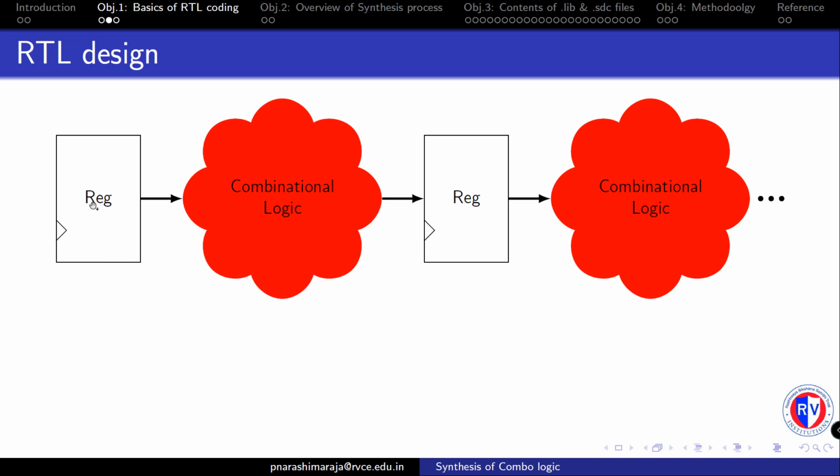One is the registers, which is a sequential logic. The other is the combinational logic. Registers, usually implemented as D flip-flops, synchronize the circuit operation to the edges of the clock signal. Combo logics perform all logical operations in the circuit, and it typically consists of logic gates.